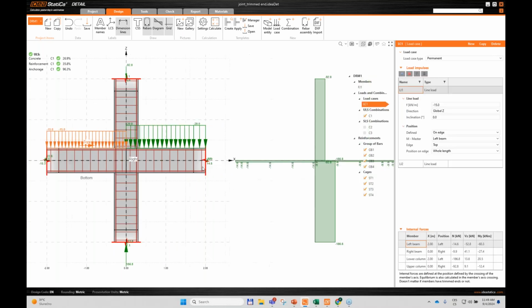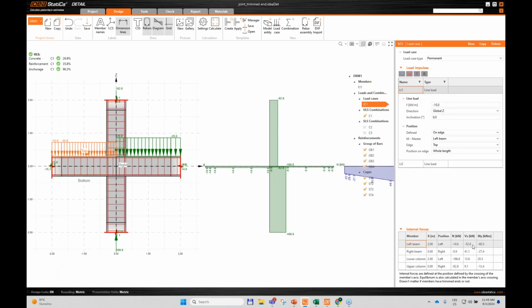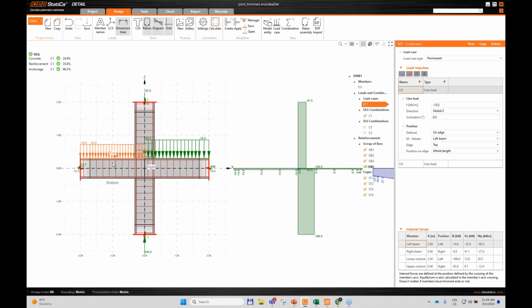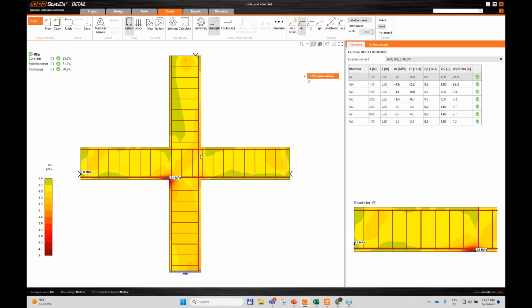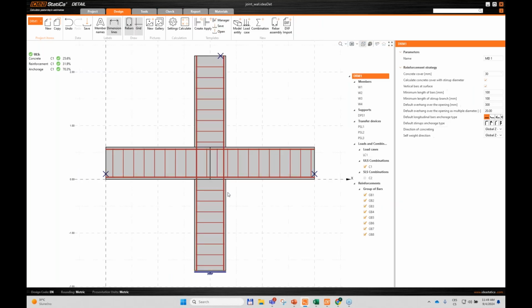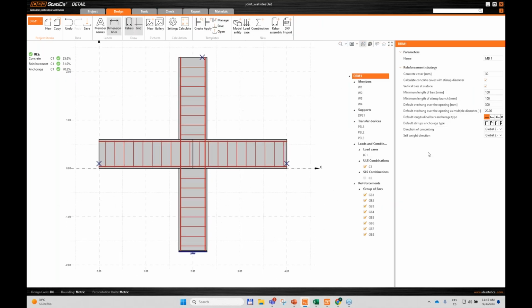You are basically inputting internal forces from your global model, and the software calculates from these internal forces and the load the forces that are applied to the model. So it automatically does what I did manually in the example where it is modeled by me.